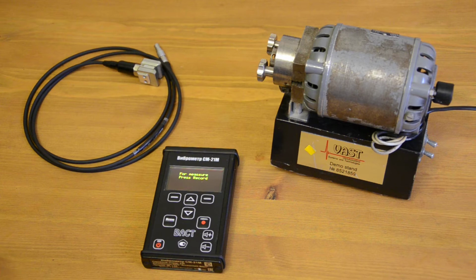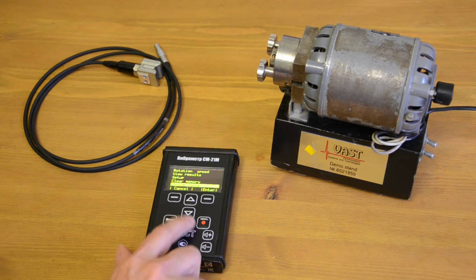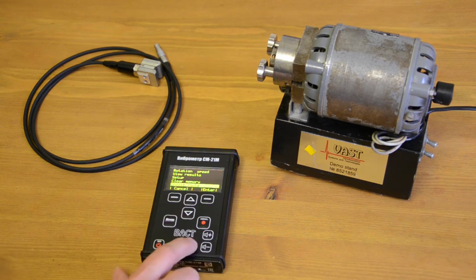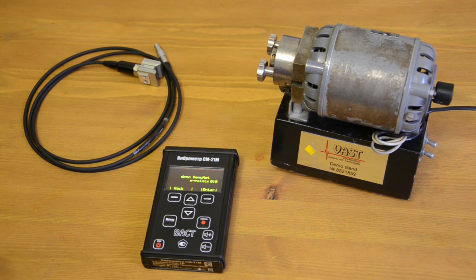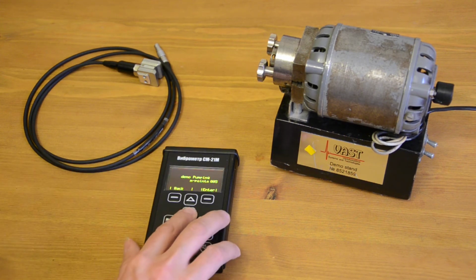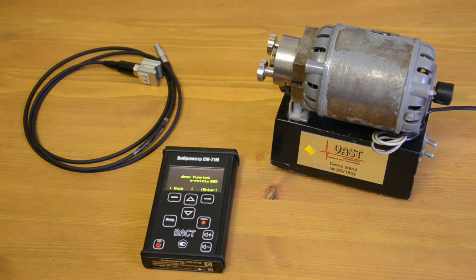In this way it will collect data according to the route that you have made in the software and then downloaded to the data collector. Once we did it, we go to the menu and there is a command like choose route. We enter it and we have a lot of different routes here. For example, a route for 10 points, a route for 5 points, etc. So to start with the data collection and with the route measurements, we need to go to the software and set up the database. Let's do it.